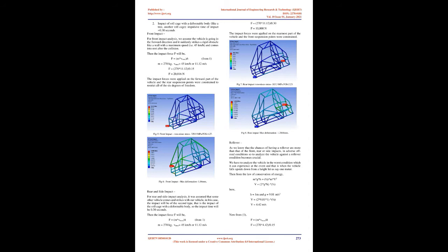given in the rulebook. The cross-section was selected after calculating bending strength and bending stiffness of primary material, and the calculated figures are as below. Material used, AISI 1018. Yield strength, Sy, 418.82 MPa. Young's modulus of elasticity, E, 205 GPa. Outer diameter, Do, 25.4 mm. Inner diameter, Di, 19.4 mm, thickness equals 3 mm.